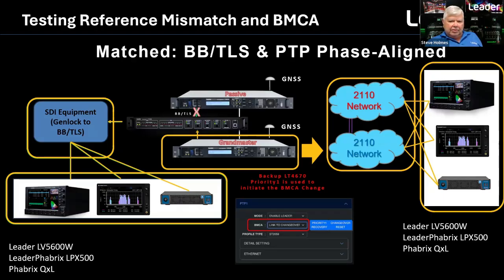PTP was not invented for the 2110 world. PTP has been around for many, many years, long before we decided to use it for video data in a 2110 environment. In the data world, the telco world, they use it with auto recovery. So if something happens, it switches over to the grandmaster switch, and if the signal comes back, it auto recovers and walks right back. We don't like that in the video industry. We like to be in control, just like we do with the ECO in the SDI world.